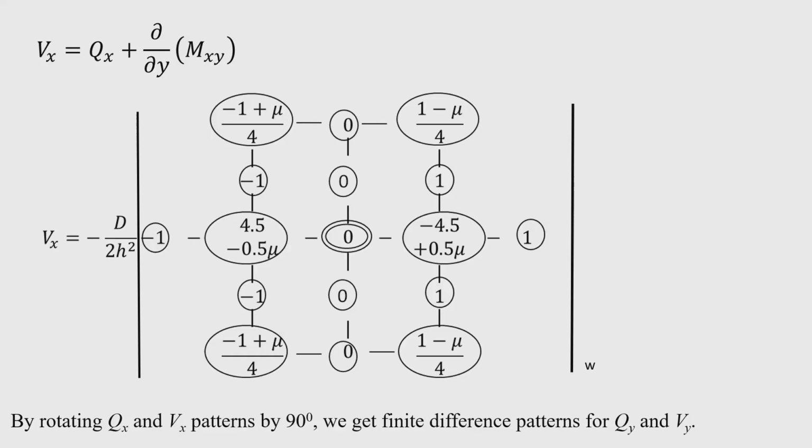Vx equal to 0. So, instead of the 3 equations that we earlier told, that mx equal to 0, qx equal to 0 and mxy equal to 0, we now write 2 conditions, where qx and mxy are combined. After combining these 2 terms, we get the S shear force Vx. The S shear force also contains the third derivatives, the odd derivatives, and this also appears antisymmetrically. So, antisymmetric values are noted in the quantity Vx.